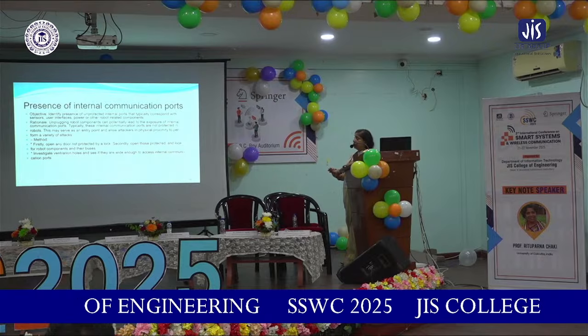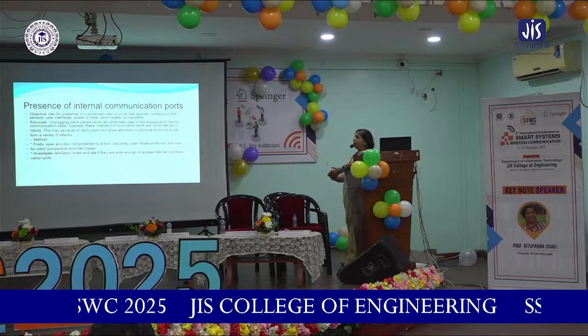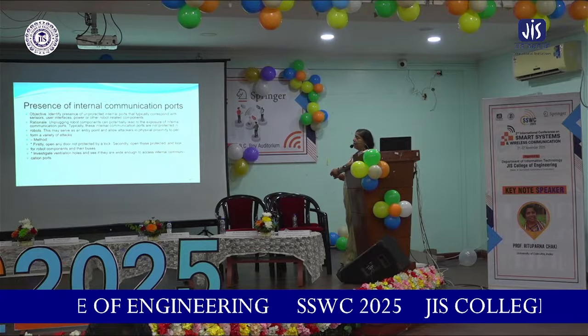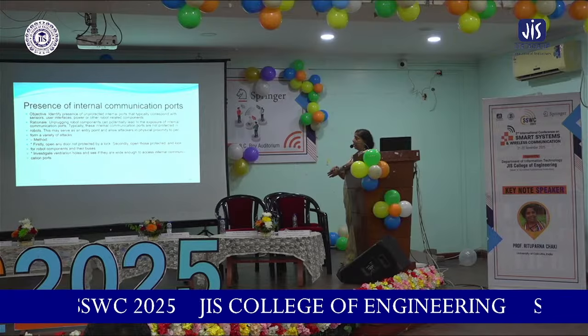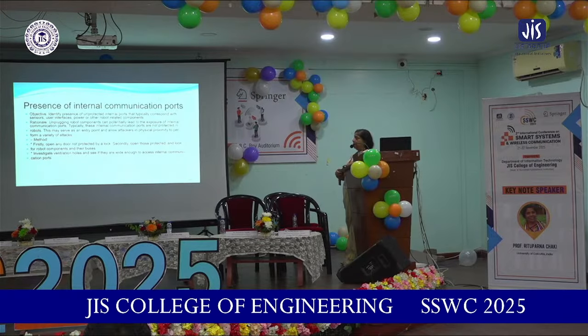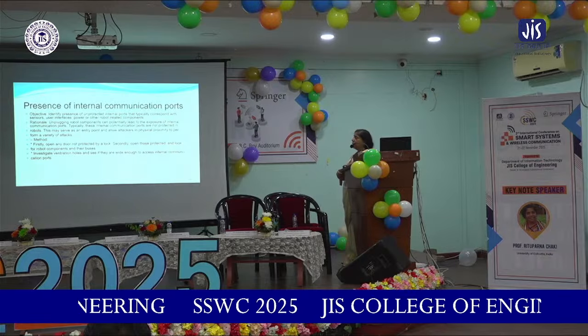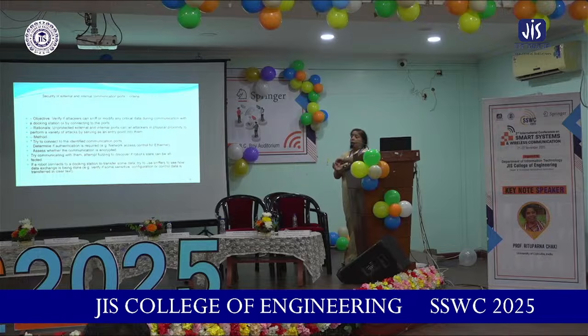So they may serve as an entry point and allow attackers in physical proximity to perform a variety of attacks. So what we do is, it's basically opening any door not protected by a lock, and then open those protected and look for robot components and their buses, and then investigate ventilation holes and see if they are wide enough to access internal communication ports. So this is about the ports.